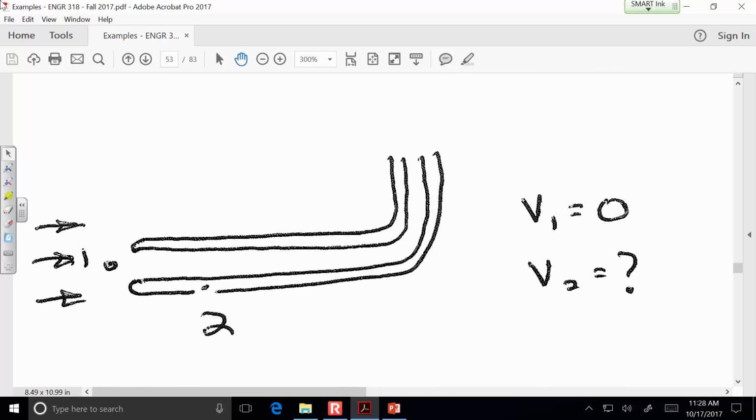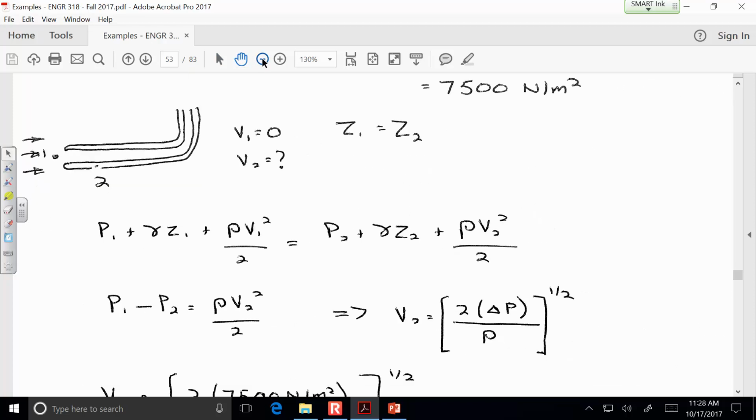A better location for it would be just on the outside, because inside the pitot tube conditions are static. There's actually no movement of fluid inside the pitot tube. So just on the outside of the pitot tube is the passing by wind speed that we're trying to calculate. So I'll adjust that drawing.